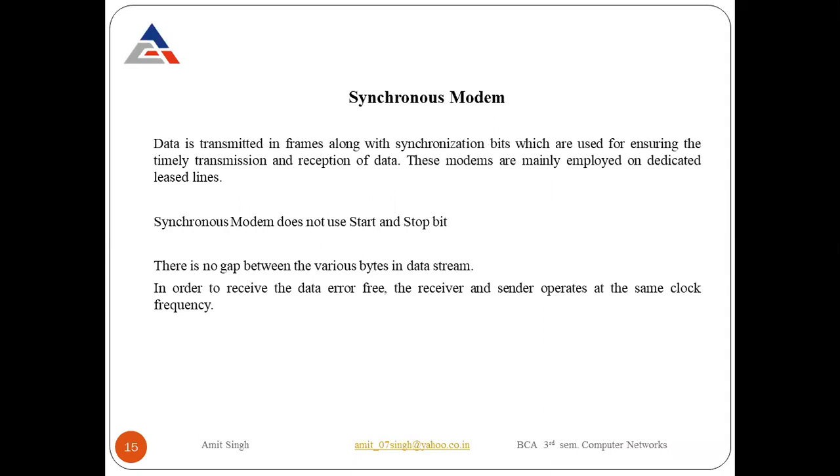Synchronous modem does not use start and stop bits. No start bit is there, no stop bit is there. There is no gap between the various bits in a data stream. No gap. What it means is that the bits are sent continuously in the form of synchronous modem. No start and stop is there. Continuously they send the data.